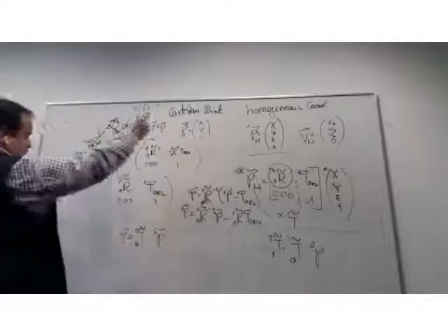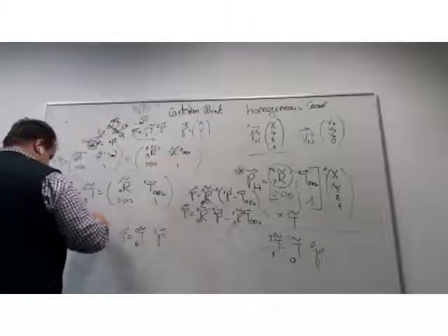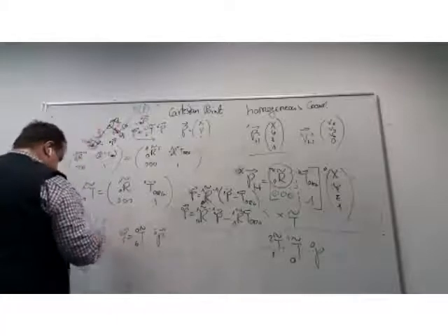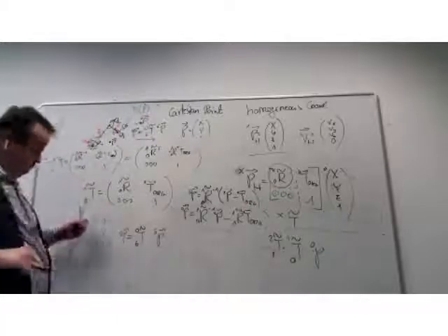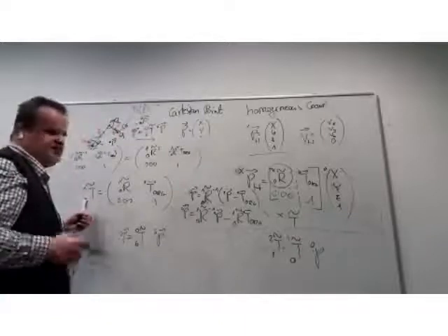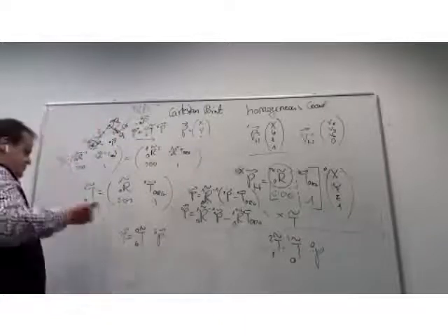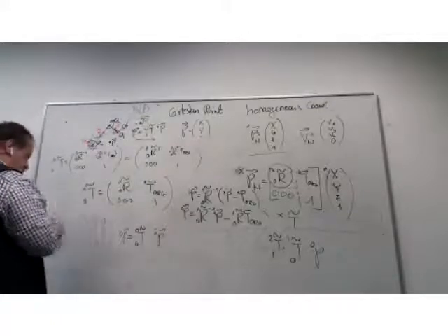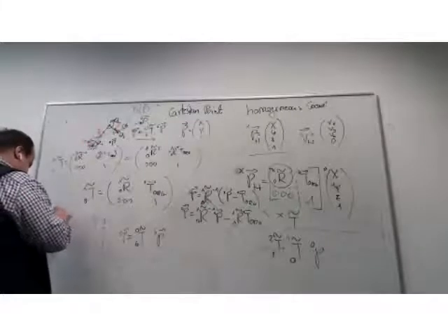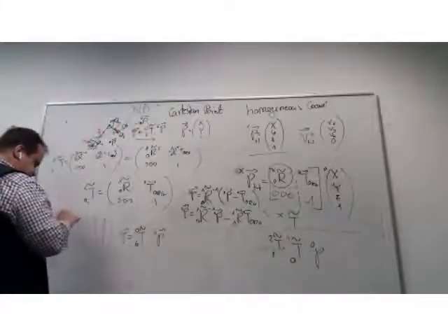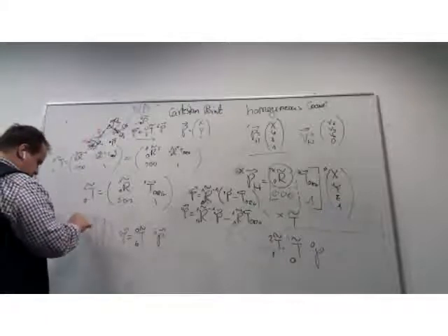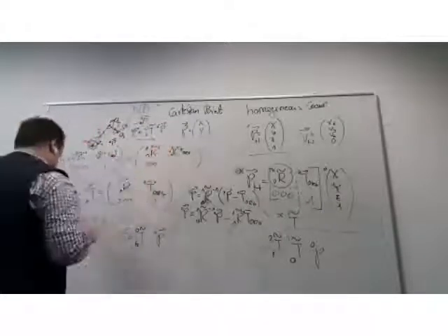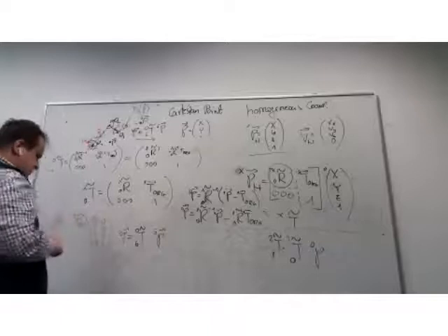And now I take this 0, 0, 0. I need to extend the homogeneous coordinate in the coordinate plane of the wrist. I assume it's a 6-dimensional, a 6 degrees of freedom robot. And I get here the rotation matrix, which rotates 6 to 0. I get the translation vector between the origins, which gets calculated exactly like this, now expressed in the 0 plane.